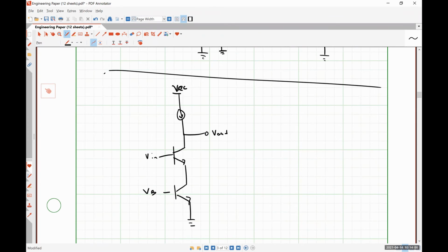Can you still use negative GM R out for that? So negative capital GM times R out, absolutely. That works for any amplifier circuit. Doesn't matter if it's BJT, MOSFET, literally anything. But is the assumption that capital GM is lowercase gm correct? Probably not, for non-Cascode. That assumption is only valid for Cascodes.